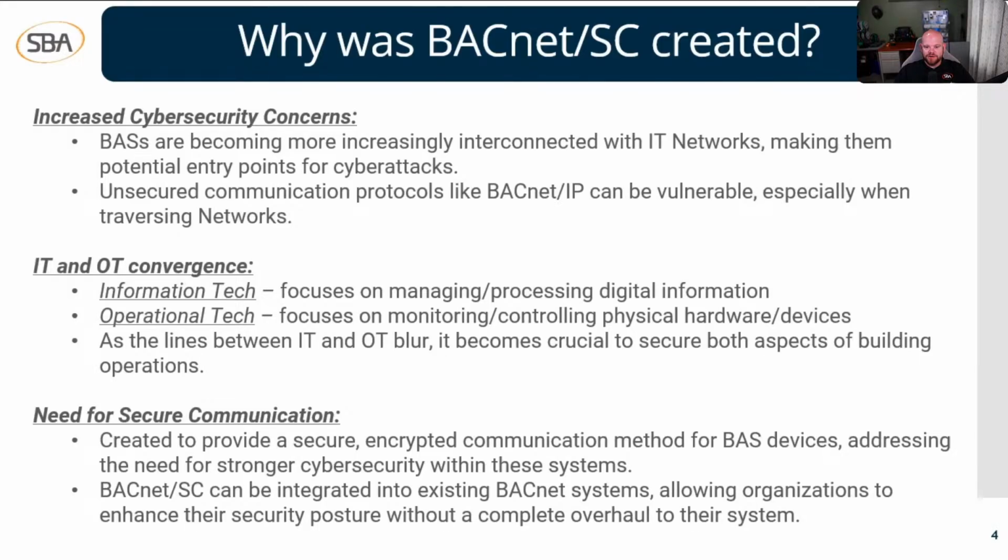All right, so now let's talk about why there was a need for BACnet Secure Connect. So why was it created? The first thing is because there were increased cybersecurity concerns. And the couple of points I have here for this is that BASs are becoming more increasingly interconnected with IT networks, and that makes them potential entry points for any cyber attacks.